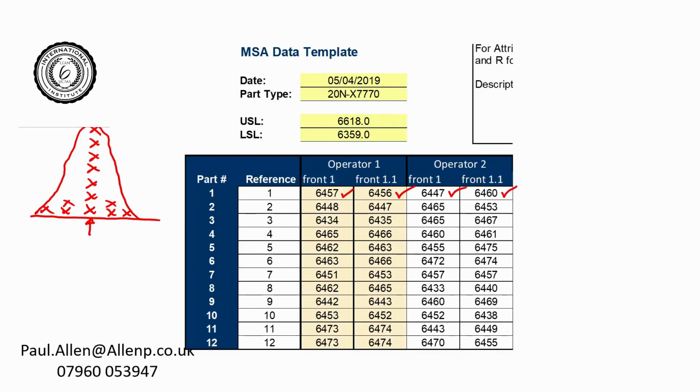Normally you would be measuring parts, but we've made sure that there's no variability in the parts. And because there's no variability in the parts, of course the maths is going to say, well, all the variability is in the measurement system, which is exactly what the results actually tell us. So that's the first thing. These measurements should have been on different speeds, not on the same speed.